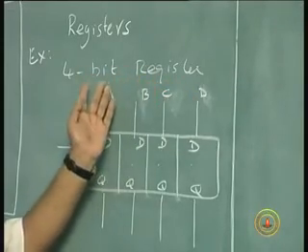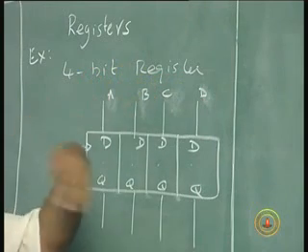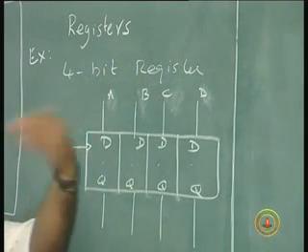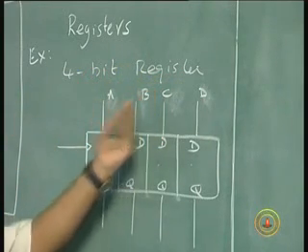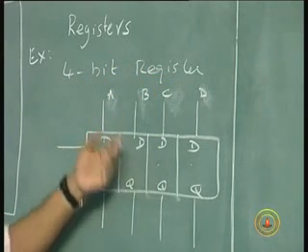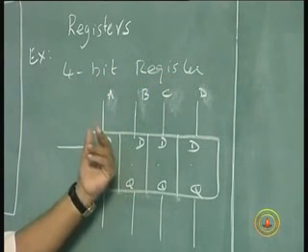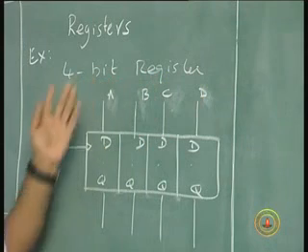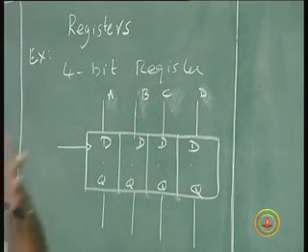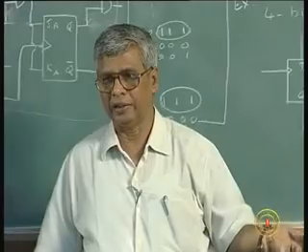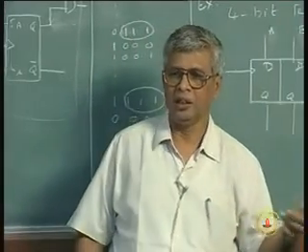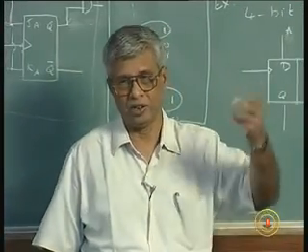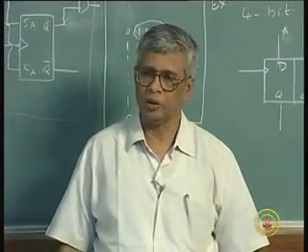related arbitrary values. They can all be zeros, they can all be 1, or there can be any random combination of zeros and 1. And the next clock pulse will overwrite my data. The next clock pulse will put this random junk into my flip-flops, so my stored data gets corrupted, or as I call it, cleared, corrupted, erased, whatever term you want to use.